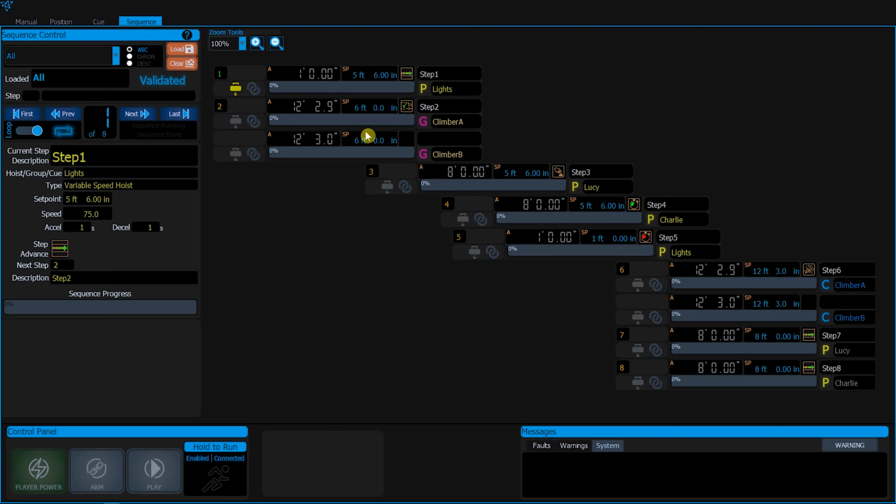On the other hand, Step 3 starts at the conclusion of Step 2, as it needs to wait for the completion of Step 2 before initiating. Moving forward, the start of Step 4 is contingent upon the operator selecting the Advanced Step button. TALOS conveniently places this type of step advance condition at the midpoint of the previous step. Step 5 is slightly offset from the start of Step 4 because it begins after a delay following the initiation of Step 4. Similarly, Step 6 is slightly offset from the end of Step 5 as it starts after a delay following the completion of Step 5.